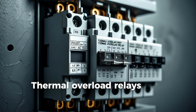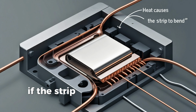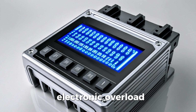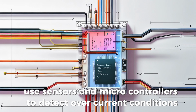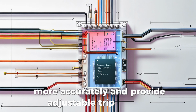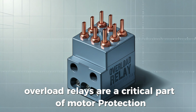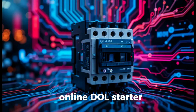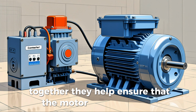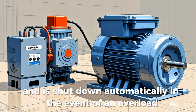Thermal overload relays use a bimetallic strip that bends with heat generated by current flow. If the strip bends too far due to excessive heat, it trips the relay. Electronic overload relays use sensors and microcontrollers to detect overcurrent conditions more accurately and provide adjustable trip settings and advanced diagnostics. Overload relays are a critical part of motor protection and are typically combined with contactors in a direct online (DOL) starter. Together, they help ensure that the motor operates safely within its rated limits and is shut down automatically in the event of an overload.